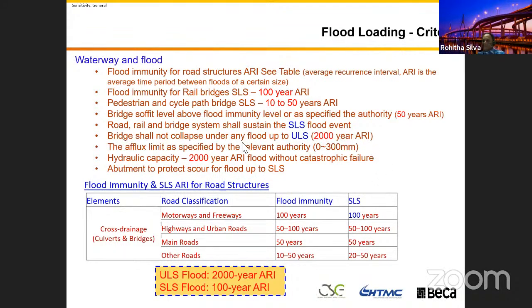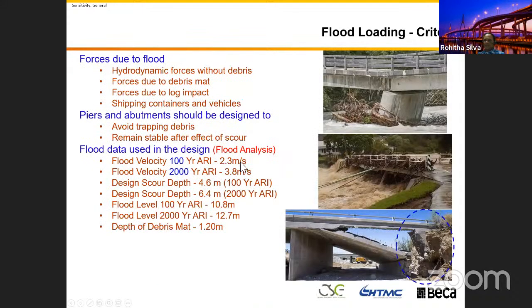We say 1 in 100 year, you should not see that sort of flood in your lifetime. And yes, we design for it. That's why I included this slide. You have seen this one before, and you have seen this one again. The flood design criteria, I put these values in here. So when you are designing for the flood, it's the forces related with the flood. It's because of the hydrodynamic force, and with the debris, and sometimes a lot of logs or pontoons, or sometimes even houses come and impact your bridge.